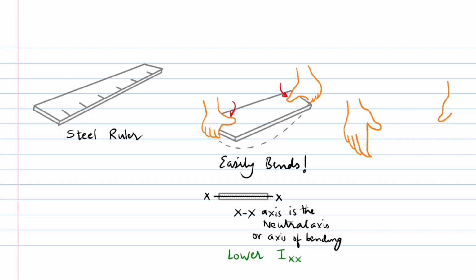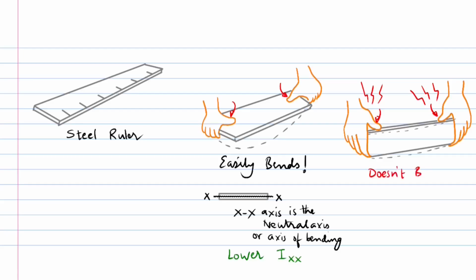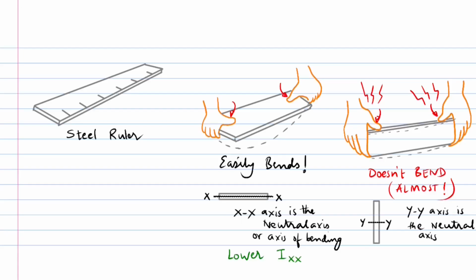As you shall see shortly, it is found that the area moment of inertia about the y-y axis is much higher than the area moment of inertia about the x-x axis, hence the difficulty in bending about the y-y axis. All the beams used in the construction industry and in machines other than the circular cross-section ones have their depth values larger than their widths for the same reason.